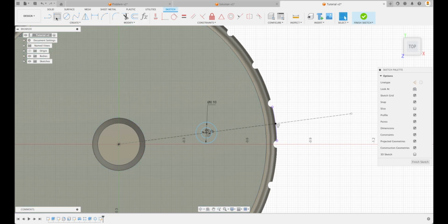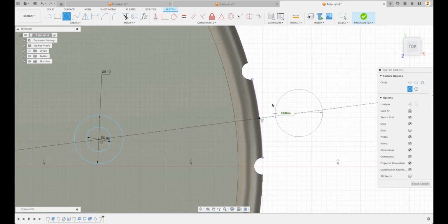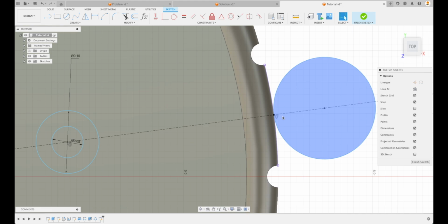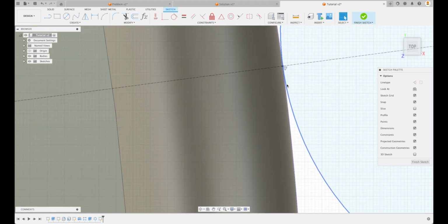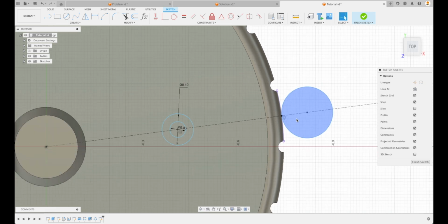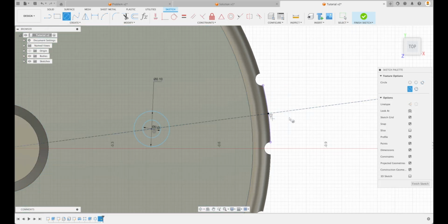There we go. And on the outside over here, remember, we don't want to make this circle tangent to that. We could, but the problem is that in real life, to 3D print this or to do whatever, to have an absolute minimum space over here, remember that's going to be a minimum space there of when it's tangent, there's actually no material for it to hold on. So we want it to be inset a little bit. Let's do that. We're just going to erase that circle.